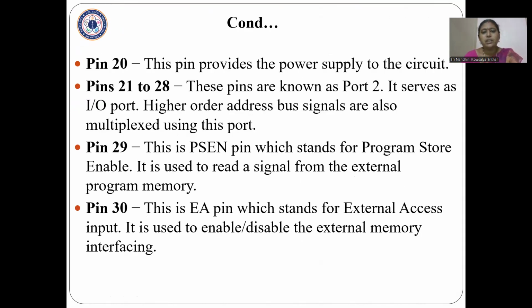Next, pin number 20. It is the ground pin, to connect to the ground. Next, pins 21 to 28. These pins are known as port 2. It serves as input and output port. Higher order address bus signals are also multiplexed using this port.